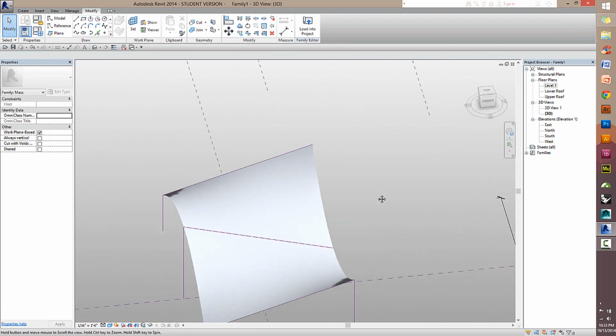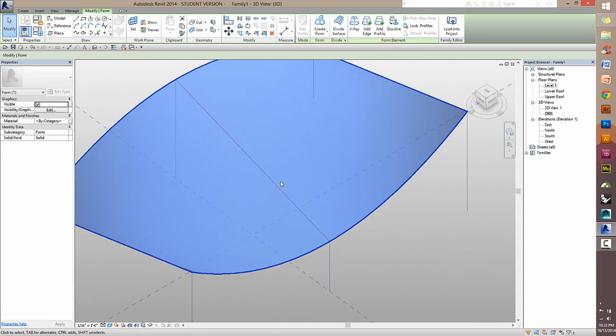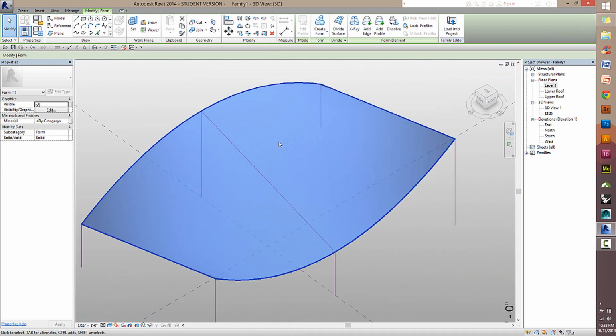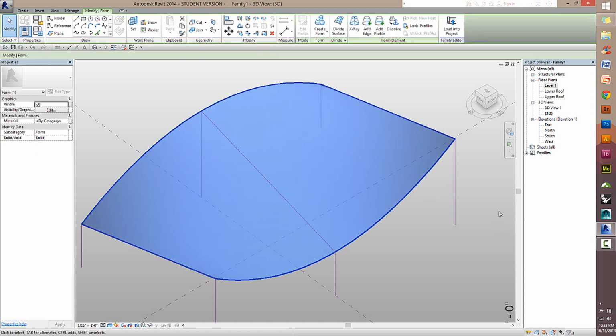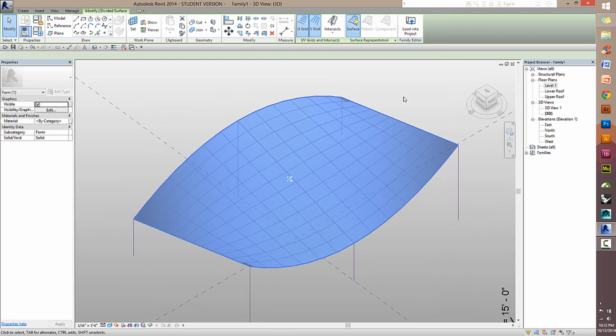All right, so that being said, we now have this roof, which I want to use as a scaffold for beams. It's really the beams that I'm trying to create a parametric model of, not this generalized shape. So since this is nothing more than scaffolding, it's important to turn it into actually functional scaffolding. And a way to do this is to go up to this Divide Surface button, click it.